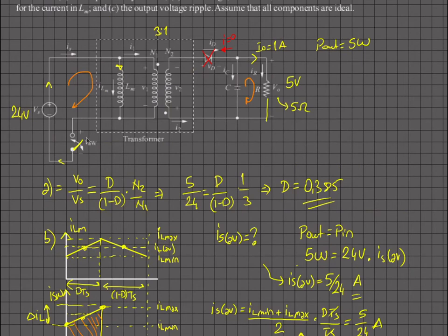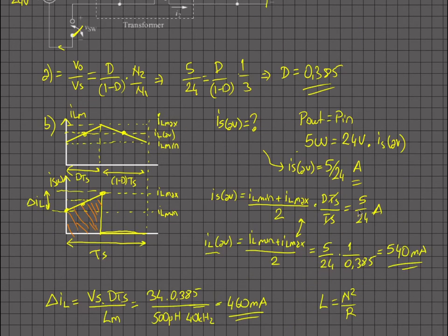Let's do the same calculation, and remember, I am just drawing current from the source side whenever the switch is on. So that's why, in order to calculate the average source current, I need to use the duty cycle. Actually that is the average, but I would like to find (IL min plus IL max) divided by 2, if I would like to find that value, right?